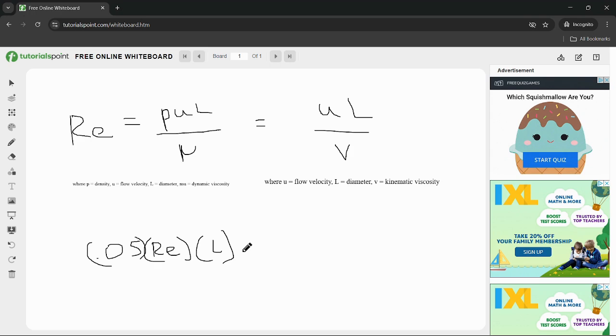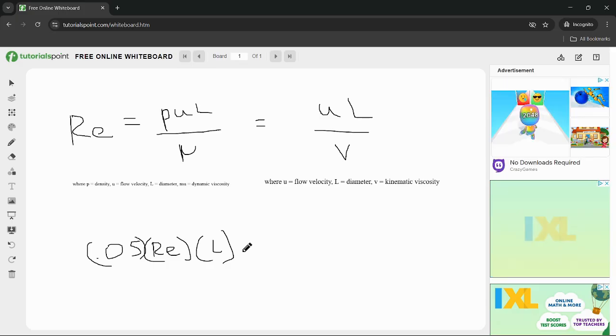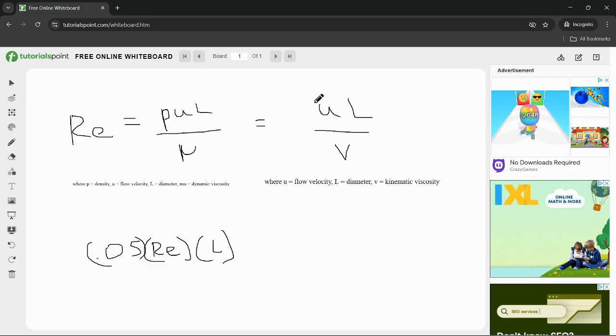And by that same token, you don't want your line scan to be too close to your inlet, since your flow may not have developed at that point. If this happens to you, you can try adjusting your Reynolds number to be lower, again by lowering the inlet velocity or increasing the kinematic viscosity. But I wouldn't lower the Reynolds number to be lower than 10, because in my experience, OpenFOAM really struggles with super slow flow.